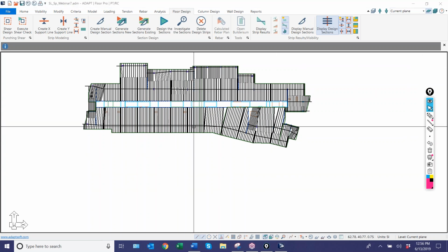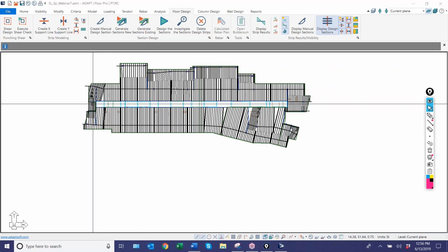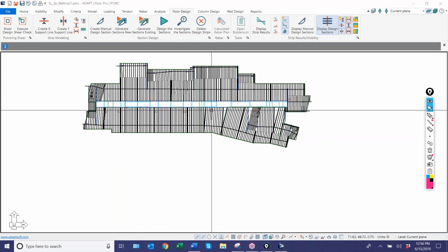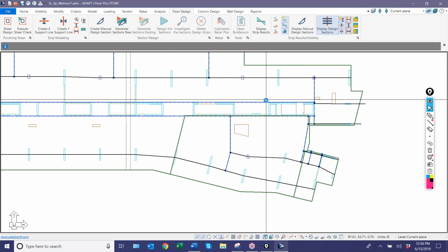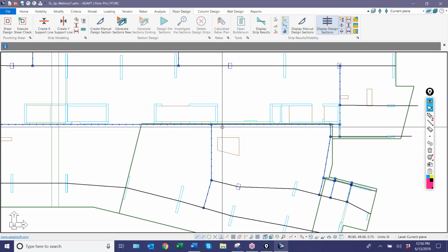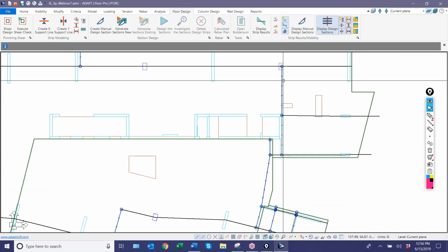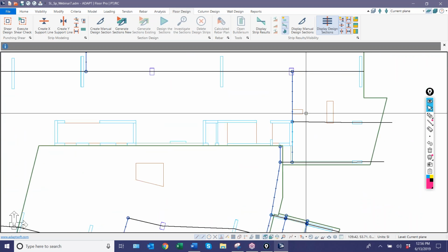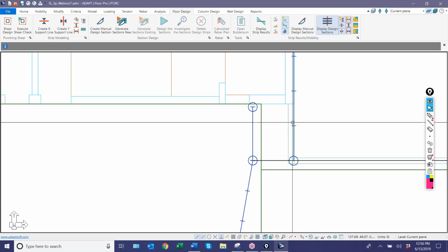We're about out of time. I'm going to go back and just show in this X direction what we would do in this case where we have all of these walls in the interior. So I'll go ahead and delete the design strips, and I'll delete out this splitter. We're going to delete out a few splitters. I'm going to delete this one, and I'll delete that support line.